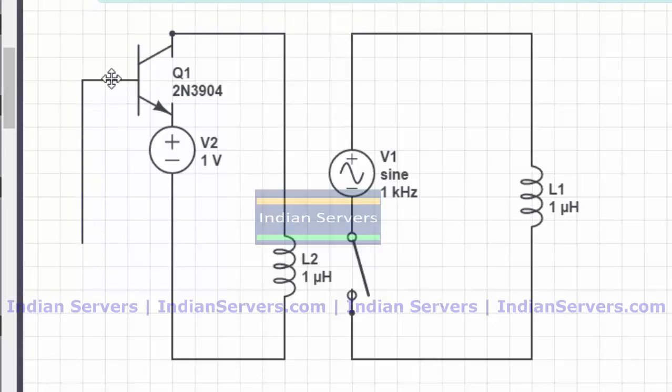So whenever the transistor receives a base signal, automatically it will turn on this coil circuit, where the coil gets energized and acts as a temporary magnet, and finally the secondary circuit, that is the circuit having higher voltage, will be activated. Like that we can use a relay for automated systems or embedded systems.